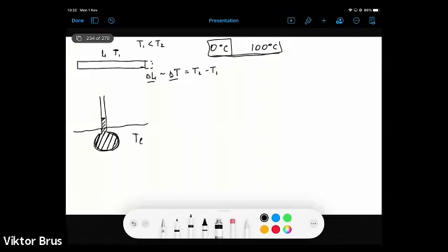And nothing can compete with mercury since it's actually a liquid metal. So we use, and that's another thing of the material science approach, mercury's thermal conductivity as a metal, but at the same time, we also use its unique feature of staying in the liquid phase at quite a wide temperature range, down to -40 degrees Celsius, which makes it really a good candidate for measuring temperature in liquid thermometers.